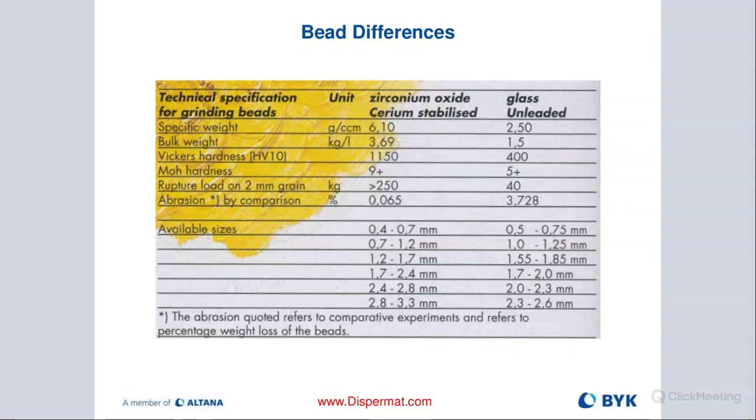And now, an important aspect is to maximize the kinetic energy, and a lot of that comes from the weight of our beads. So we want to select high quality, heavy beads. Of course, they can't be metal. In most battery applications, you don't want iron deposited inside of your mill base or slurry. So we would use ceramic beads, either zirconium oxide or yttrium stabilized, just a few examples.